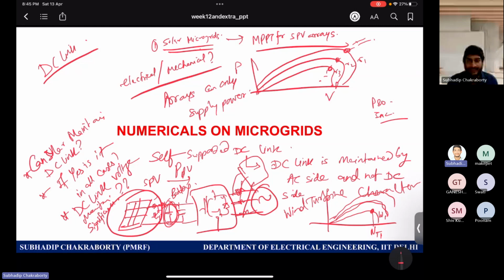If you can control the electrical torque of the generator, then the net arrangement, wind turbine plus generator, can be moved at different speeds by generating different electrical torques. Because those systems are coupled, wind turbine blades plus generator, by controlling the generator torque you can change the speed of the overall system irrespective of the wind speed.